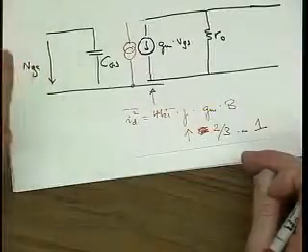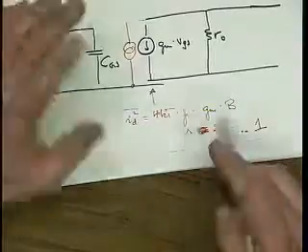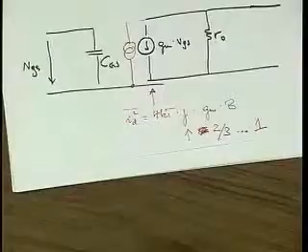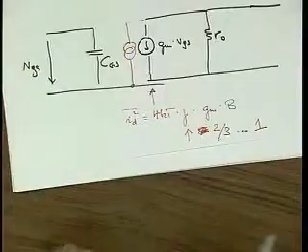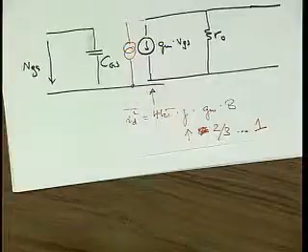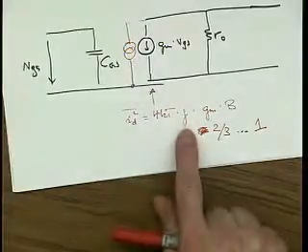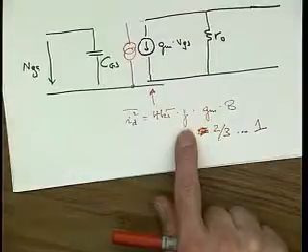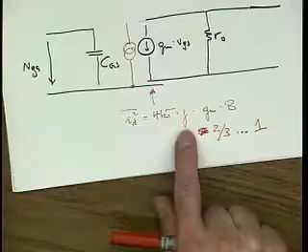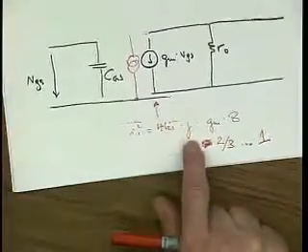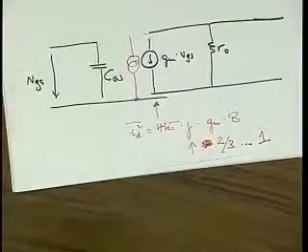There are also papers in the literature that say, oh, we've measured this for our process and it's like 10. Well, if you find such a process, then look for another foundry. In the meantime, we found out that, yes, it's possible to get a gamma of 10. I don't know how and why, but they somehow mess it up in the foundry, and there are plenty of other ones that don't. So if you get one that has an excessive gamma, just choose another one.